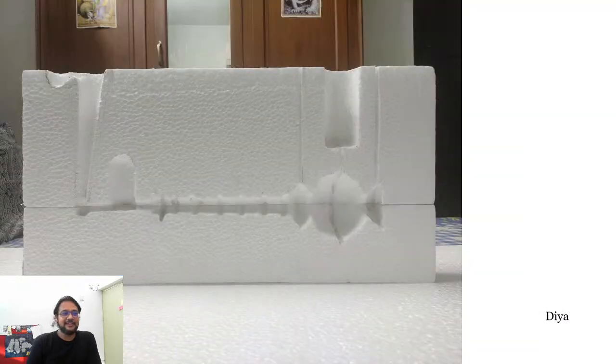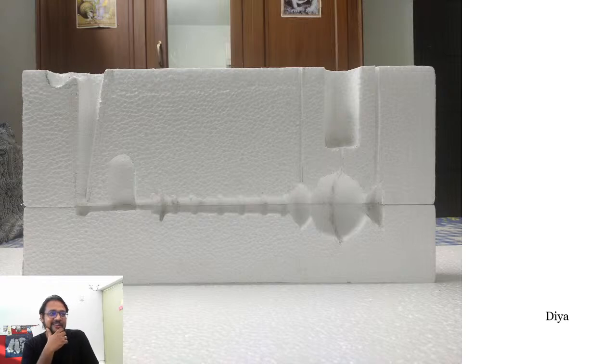This is Dia's work, and I think Dia made a casting of a diya stand, which was quite interesting, and she made it out of thermocol. The best thing that I liked about it is that she followed the details that we had discussed in class earlier. There is a pouring basin, there is a sprue, and there's a place where the turbulence of the molten material is controlled. There's a blind riser, and then there are vents at the right locations, I think. But in this particular case, you would need vents in all of these locations where there are ribs in the main casting cavity. Okay, so like this.